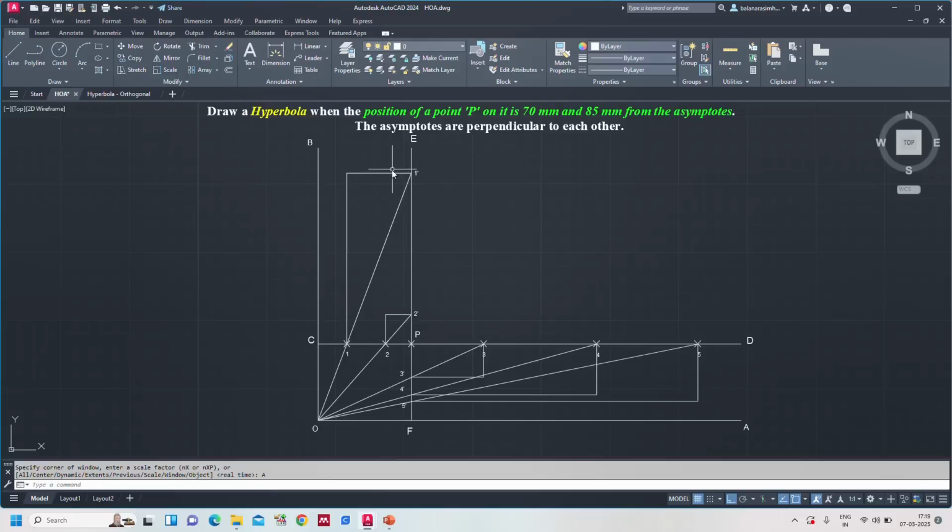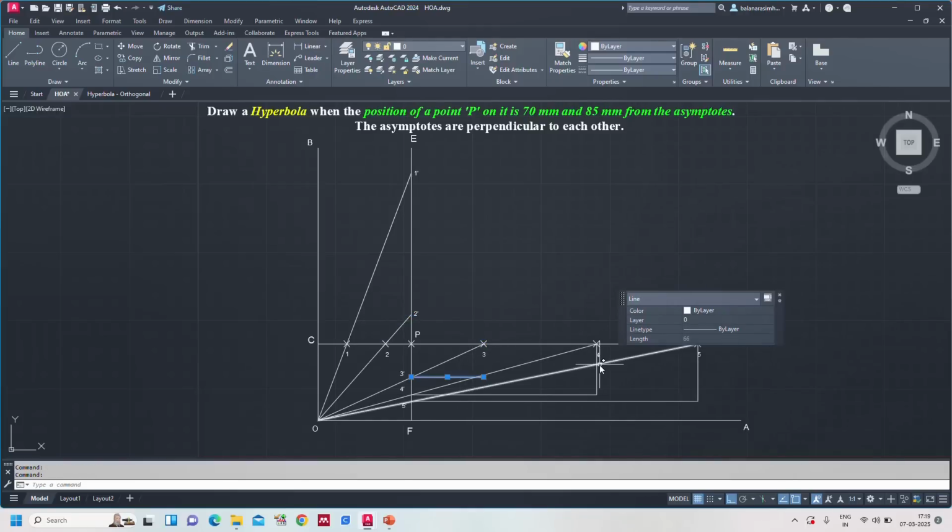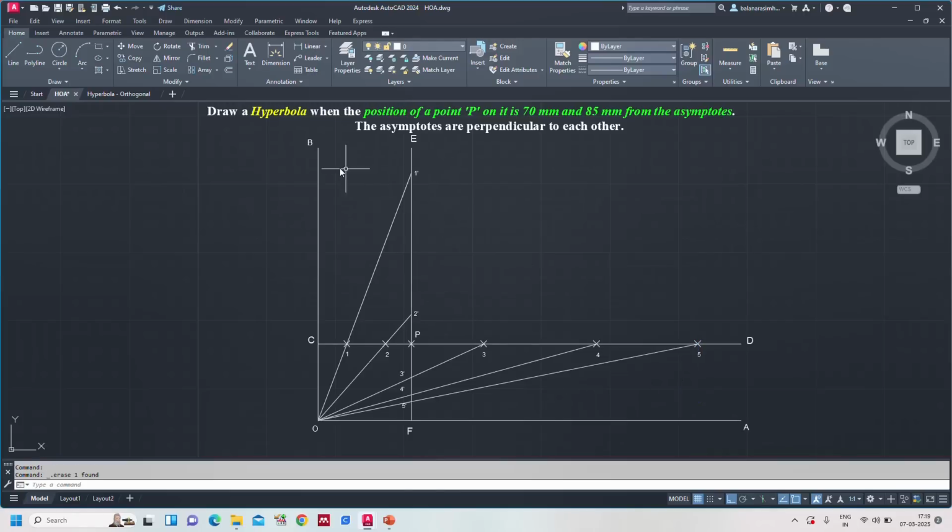intersection points. Just one more method I am going to teach you, that will be simple and easier for this one. Whichever you wish, you can follow. I am giving both. Okay, instead of drawing vertical lines and horizontal lines, the main purpose, we know, is to get the intersection points. Already I activated the object snap tracking, auto snap on.